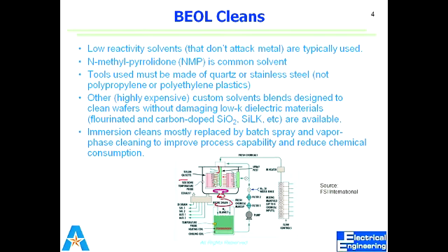Cleaning is just like that you actually etch the surface. Specifically the oxide cleanup process, that is actually, if you etch silicon dioxide, that is the same process. You go for buffered hydrofluoric acid, BHF. And in the last step, mostly the cleaning is just like you submerge your wafer in a bath or in a solution, that's named the wet chemical cleaning process, but that has also been replaced by some other technique named the vapor phase cleaning.